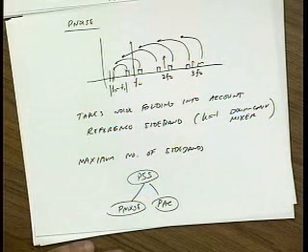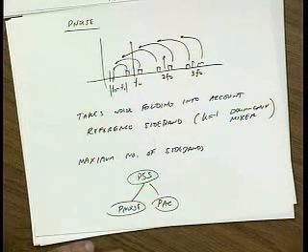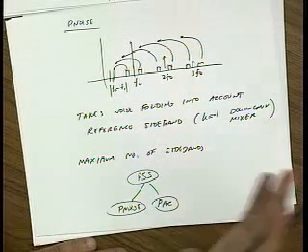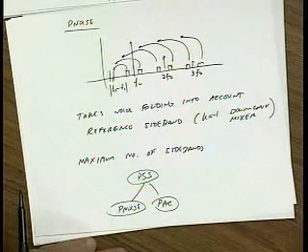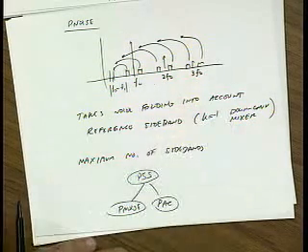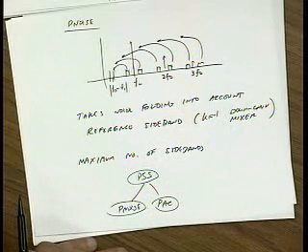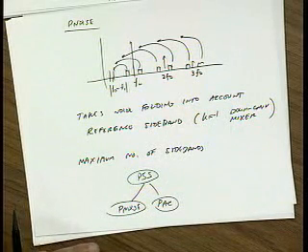Yeah, it's a good question. You can tell it if you want integrated noise or spot noise. And you have to also tell it where your input and output port are. So it's a lot like just doing regular noise analysis in that way. It also gives you a nice noise summary, so it'll tell you where all the different noise sources are, and what their contribution is to the total output noise.